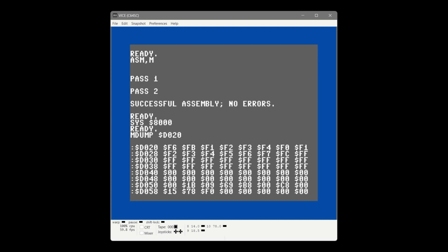So that particular register that's exposed by the VIC chip actually only stores a 4-bit value. Each one of these digits in a hex number represents 4 bits of the 8-bit value. So this side here, where the cursor is, is the only part that the VIC chip cares about, because it's a 4-bit value, and that holds the numbers between 0 and 15, which is F, hence why we have a 16 color limit. And whatever number you put here is just discarded. The emulator shows me an F here. What I don't know is if on real hardware, this number is random or not. So if anyone has this on real hardware, I'd be really curious to know.